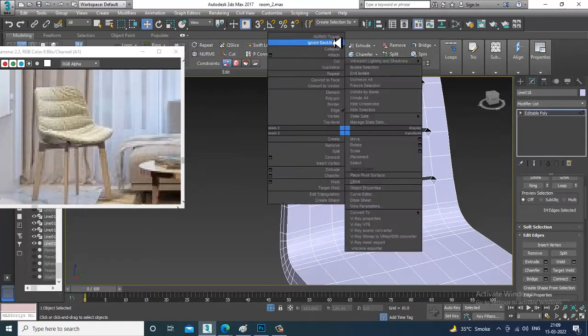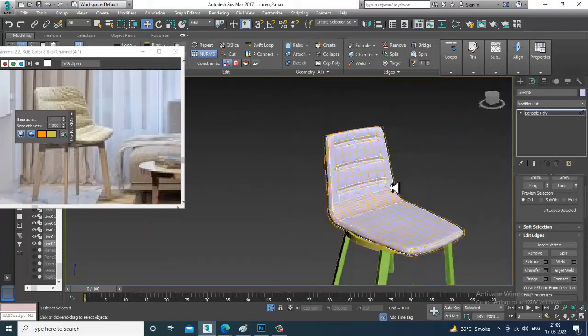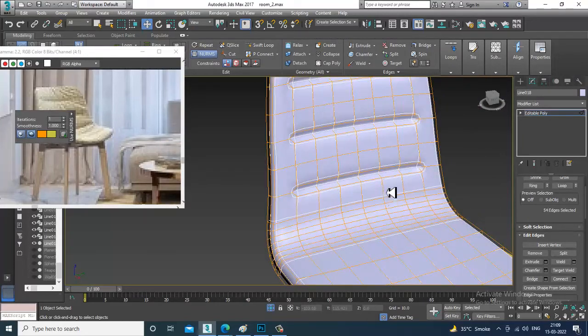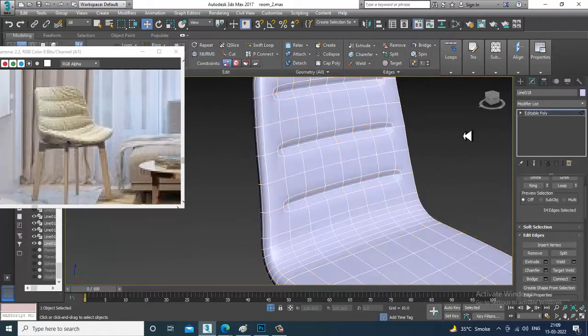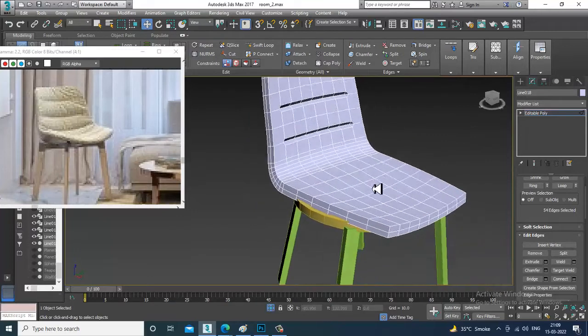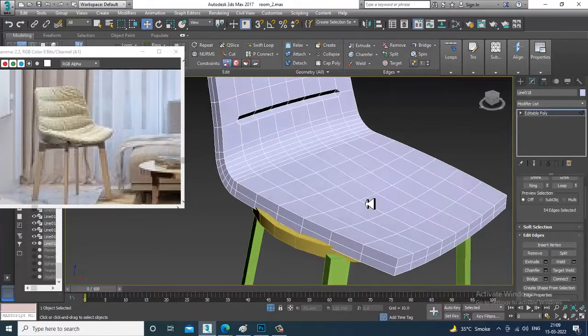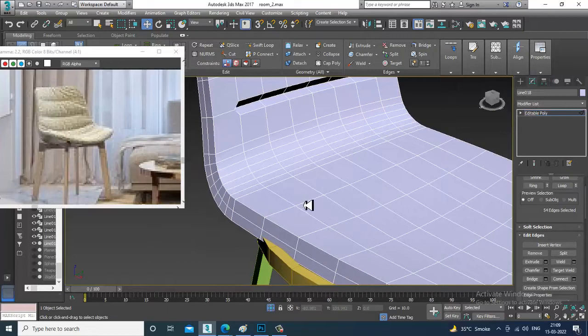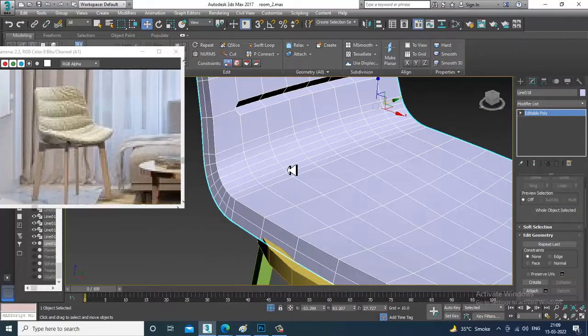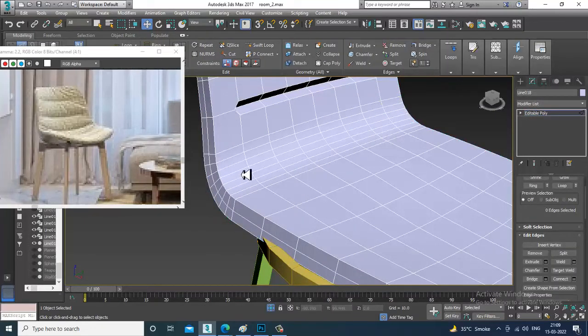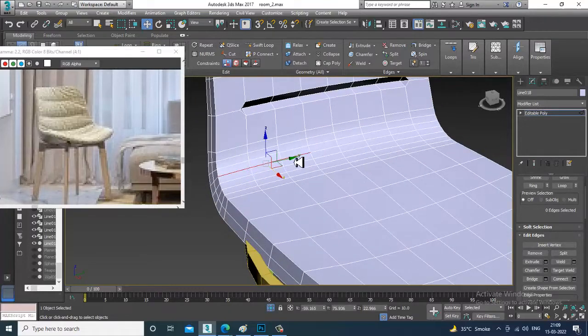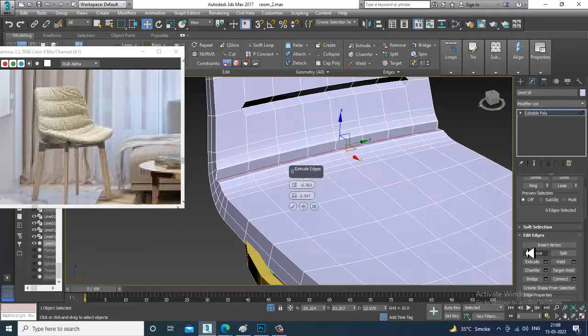If you want, you can see with the knobs toggle over here. I can deactivate it again over here. So again I'll go over here and again I'll take the edges section. So select all the edges over here, and let's give a bit of extrude.